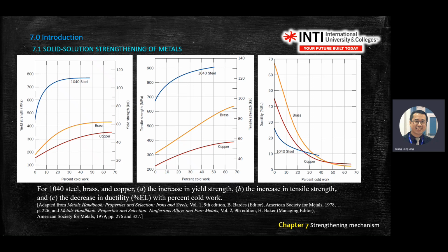So for example, the customer wants the end result to be 300 megapascal. So you draw a line and then you go down and there's a percentage there. Then you move to here. It will give you, after the process, let's say you have 12 and 35%. You have two, there's a range there. Then it tells you the tensile strength of that final product.